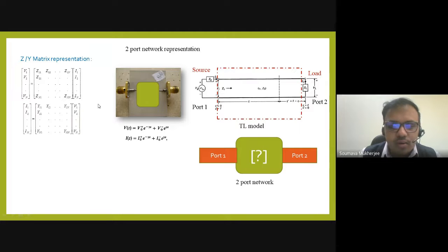So then people figured out, okay, fine, these are not constant, this summation is changing, but there is something which is constant. What is constant? Constant is the reflection coefficient, because that is only a function of the load impedance and the characteristic impedance. Once it is fixed, we know that for this circuit this is constant. So if we can relate our matrix circuit representation in a matrix form from those quantities which are constant, then it will be much more helpful for the mathematical calculation.